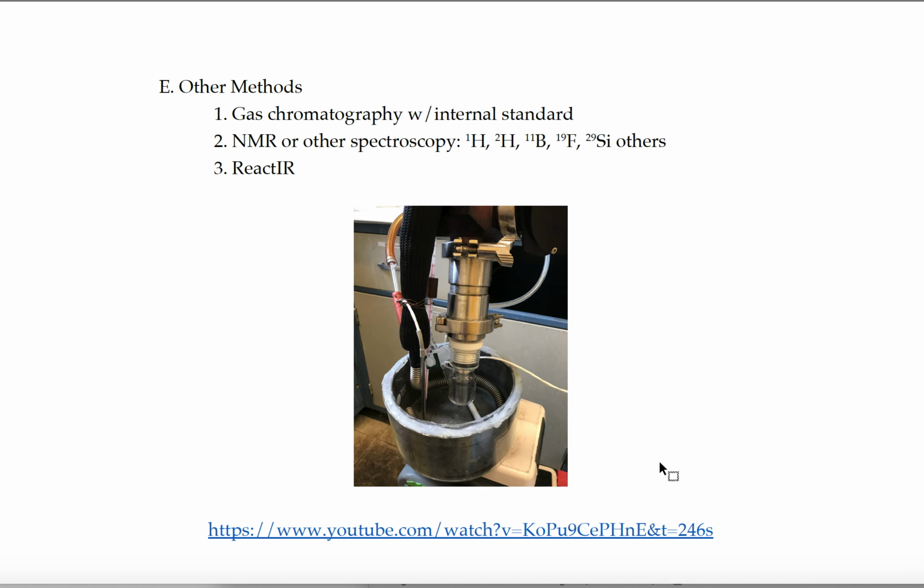And I do have a point here, and that is you needed a factor of 40 to do the kind of kinetics we wanted to do. And they found me the factor of 40. And how do you do it? Well, if you look at this picture of our ReactIR compared to your ReactIR, the first thing you'll notice is the probe is short. It's a little snub-nosed probe. It's a 1-inch diameter probe, which means it's a 30-bounce silicon wafer.